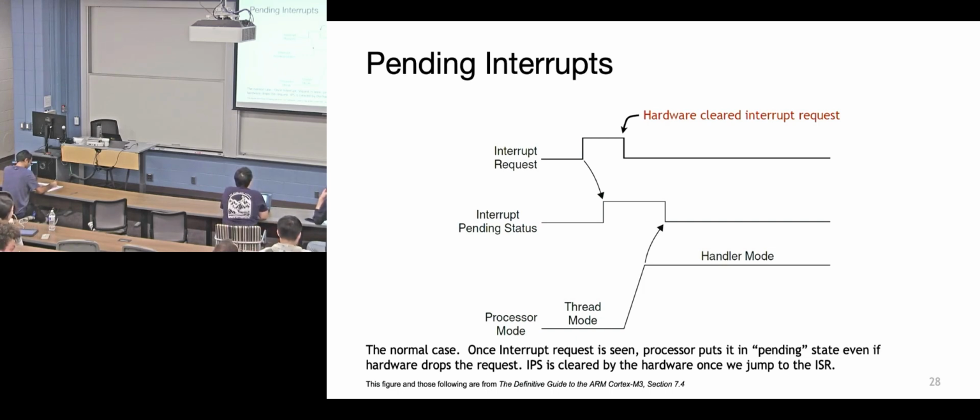The speed setting of your GPIO line, the GPIOs are not involved in here. You don't have access to it, but that's really about what sort of load you expect to have externally on your device. If you have a load that doesn't have much capacitance or has certain things going really fast, it might ring, and that would cause signal integrity issues. So that's really why the speed is there. It's basically how much drive strength you get.